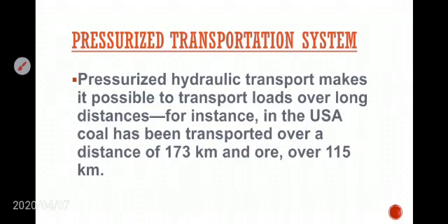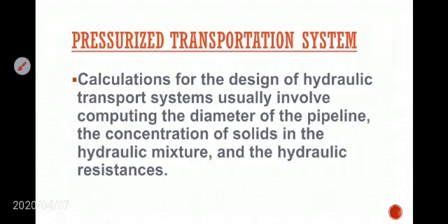In a hydraulic transportation system, it is possible to transport large loads, that means a huge quantity of mineral or slurry, through longer distances. For example, in USA, coal has been transported over a distance of 173 kilometers continuously without any interruption through this pressurized transportation system in hydraulic mining. And in the same country, ore is also successfully transported to distances of more than 115 kilometers through this pressurized transportation system.